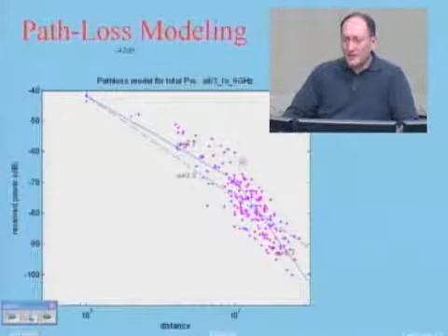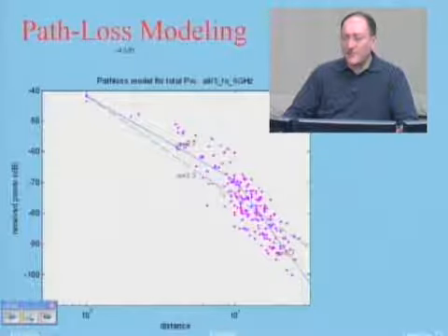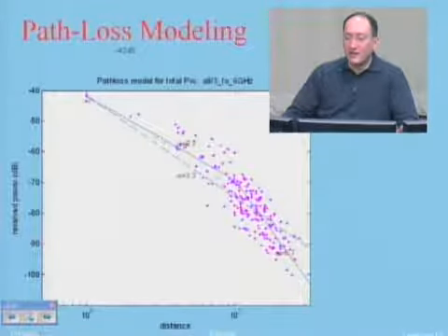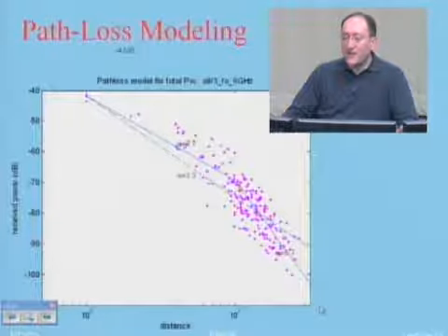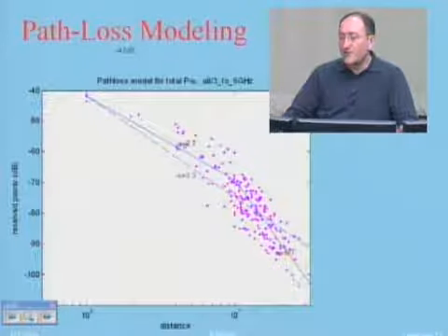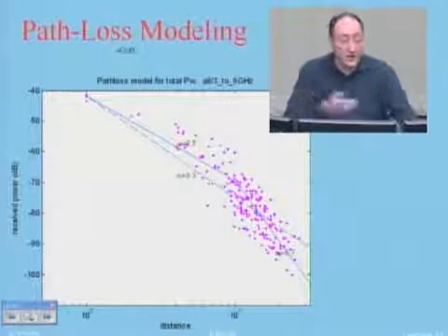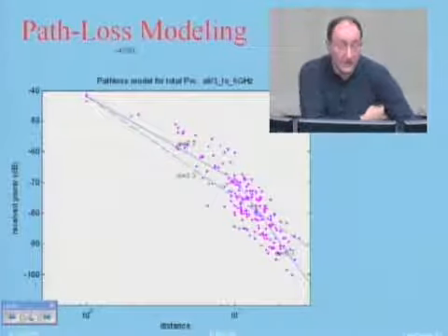But we see this pattern that at the beginning they are like this, and then I have a faster decay. Up to 10 meters, I can fit a line. After 10 meters, I can fit another line. The distance power gradient in the first is like 2.7, and in the second one it is 6.7. This is called partitioning, and we did partition models before as well.